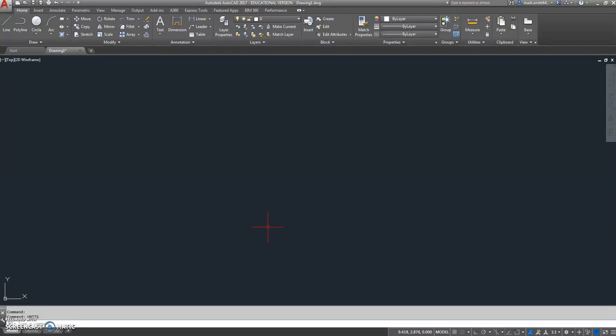So if I go to my third step, drawing limits, I'll type in limits, and our lower left should be 0,0 inside the chevrons. Notice that the decimal precision reflects what I set up. So I hit enter, and then if we look at the drawing, it says our limits are 11, 8.5, and we'll hit enter.